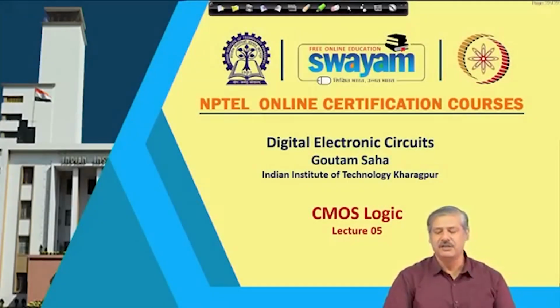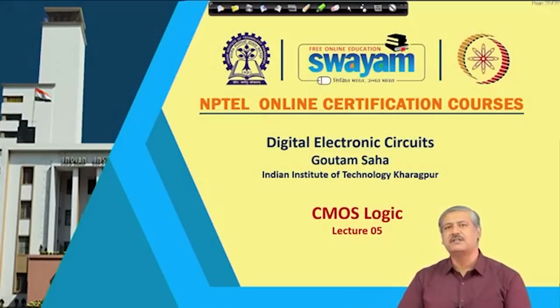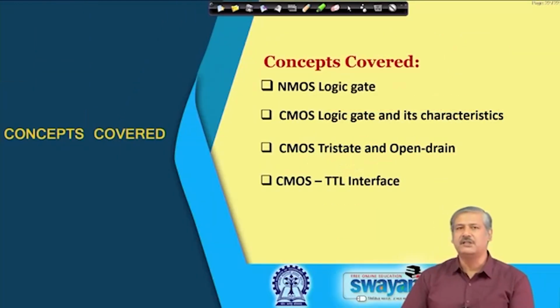Hello everybody. We discuss CMOS logic today. In the last class we discussed TTL, transistor logic based circuits, and we will cover CMOS logic, of course, and its various configurations like tri-state and open drain, and how to interface when it is used together with TTL in a circuit. But we shall begin with a brief discussion on NMOS logic.